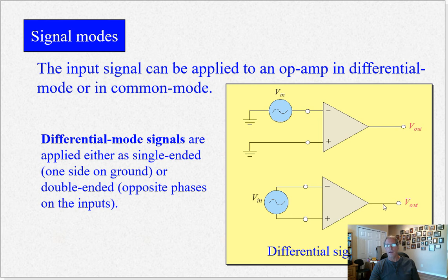However, on the single-ended one, it doesn't work that way, because ground is usually very low impedance, really stable. Your noise is going to hit the input terminal, in this case the inverting input, and the noise will show up on the output. That's why they're called balanced signal interfaces or differential.